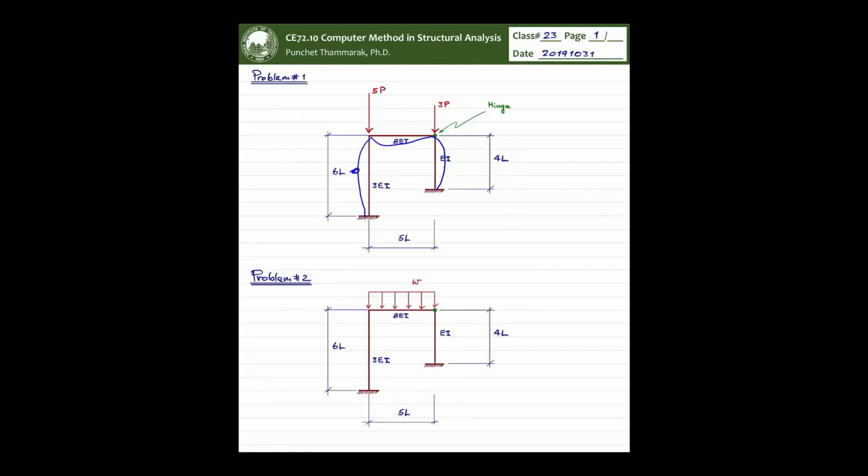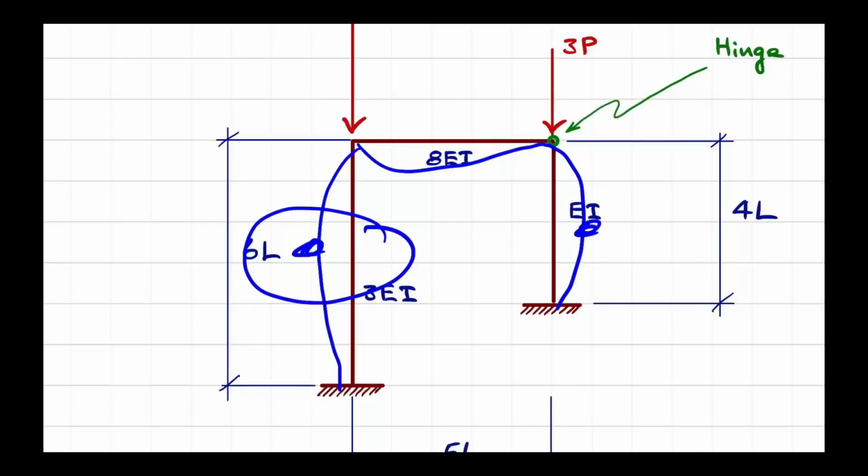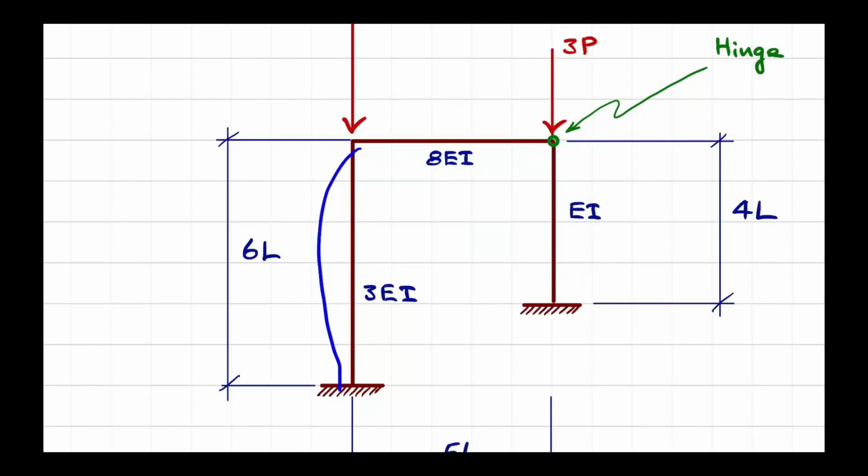Then these points are not captured. The large deformation here is not addressed by the way we set up the degrees of freedom. So to make sure that we will not end up with a situation like this, better put the node there to make sure that we at least pick up the second order moment effect.